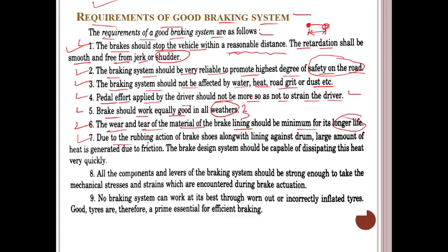Seventh, due to the rubbing action of the brake shoes along with the lining against the drum, a large amount of heat is generated due to friction. So the brake system should be capable of dissipating the heat very quickly. When we continuously apply the brakes, larger heat is generated inside the drum of the brake system, so this heat should be transferred from the system to the surroundings very fast.